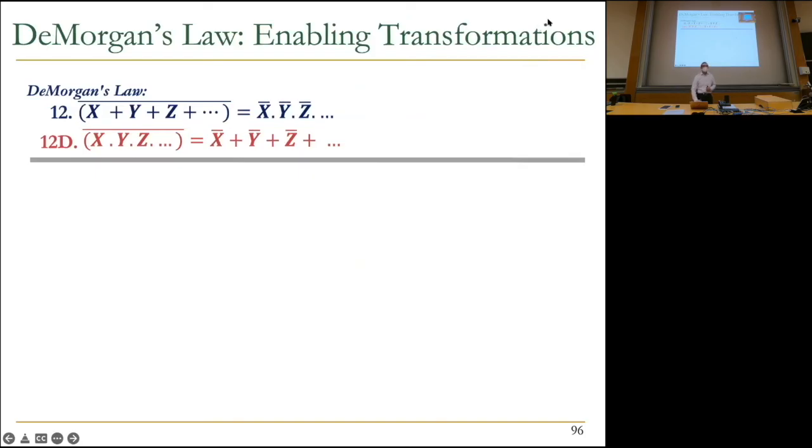Have people heard about De Morgan's laws? Okay, so many people have. So I'm going to go through this quickly also. I've been doing a lot of quick going through, as you can see. But this is really a transformation. This is what the law is, basically. OR of variables complemented is equal to AND of complemented variables. And its dual is also true. I'm not going to say the dual in terms of logical way. Well, it's very easy to say clearly.